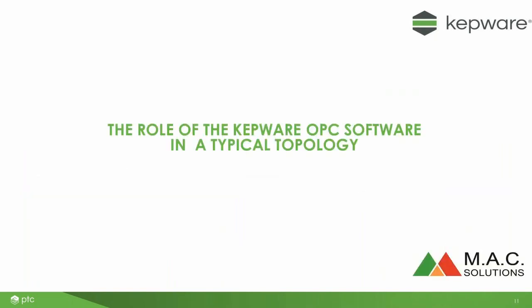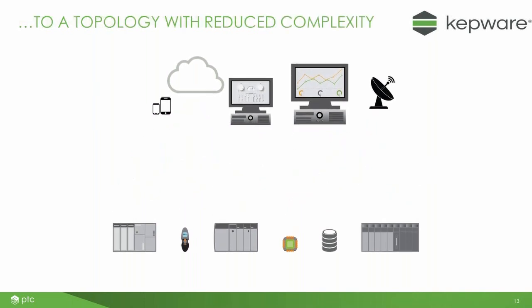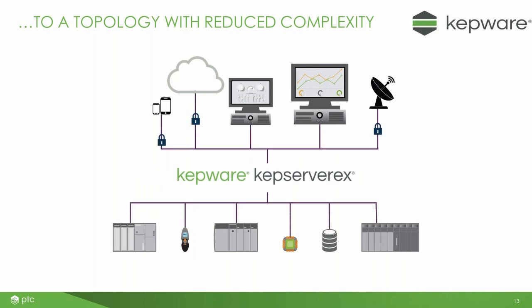So where does Kepware's OPC software fit into a typical topology? What's the purpose of it? The idea is that you move from a complex topology of lots of devices talking to lots of other devices in an unstructured way to something much more reduced in complexity. KEPServer can sit in the middle and act as the conduit, talking to all the devices below and all the systems above, in a very organized and structured way.